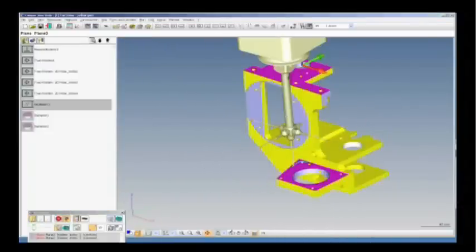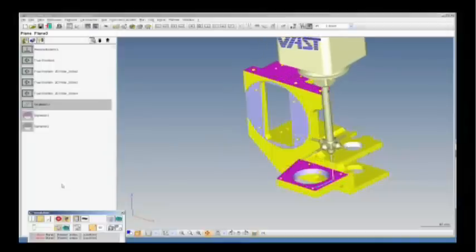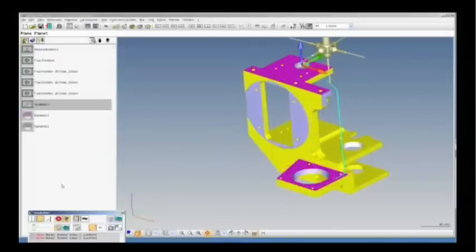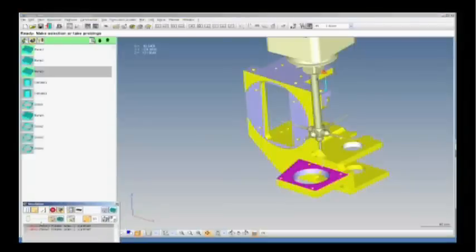And fine here in the world of simulation. It's really not that big of a deal. Calypso does really try to address as much navigation as it can. It is software. It tries to automate everything. It does its best as software can do. It's still going to make a few mistakes. Okay. So the benefit of simulating is it identifies those mistakes. Actually, down in here, it'll go right to the actual feature with the collision. Oh, so it actually detects that there was a collision and tells you, so that you can go in and fix it somehow. Yeah, it does exactly.